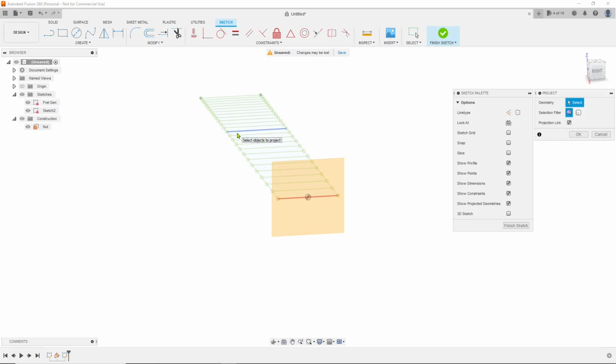It is going to come straight to this sketch. So if you had another plane over here with something drawn on it, you could still project it, but it's going to come straight up to meet this plane, perpendicular to this plane, not the plane you drew from. Just so you understand the way that works.